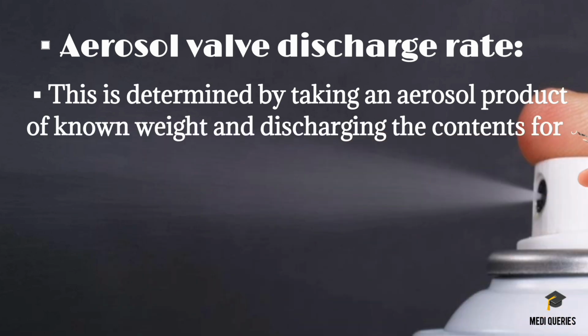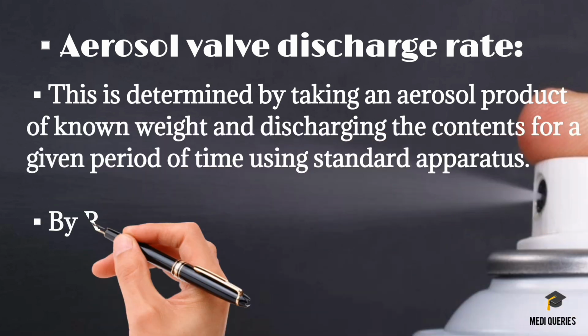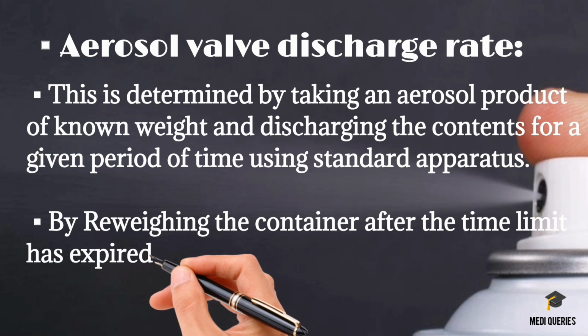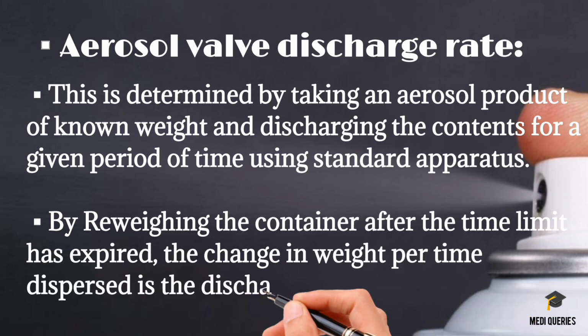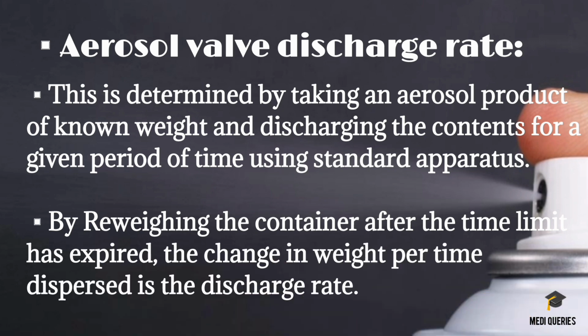Okay, and the next test is the aerosol valve discharge rate. This is determined by taking an aerosol product of a known weight and discharging the contents for a given period of time using a standard apparatus. By reweighing the container after the time limit has expired, the change in weight per time dispensed is the discharge rate, which can be expressed as grams per second.